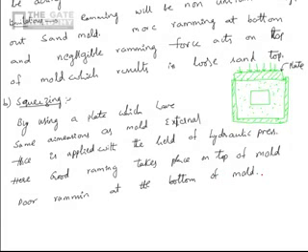In jolting we allow the molding box to fall from a certain height such that ramming action takes place due to potential energy. But here, we keep the molding box on the ground and apply a continuous compressive force on top of the molding sand. So ramming action takes place on the top in squeezing and on the bottom in jolting.